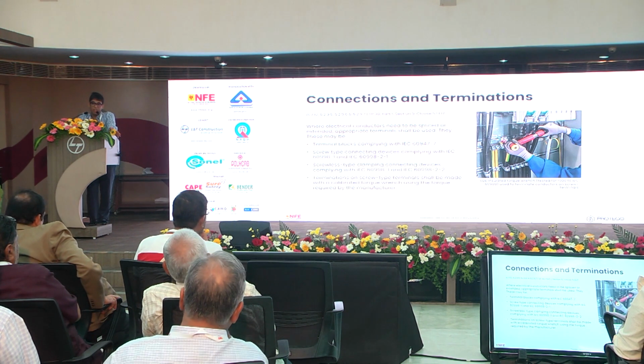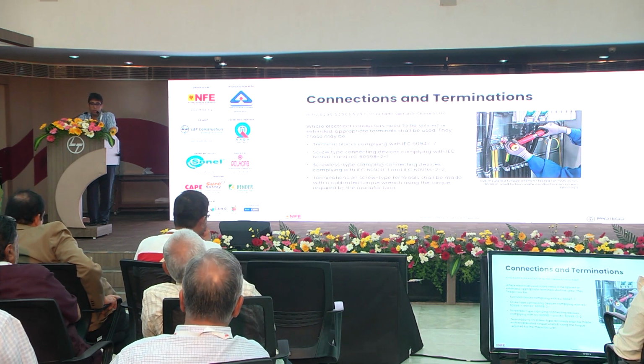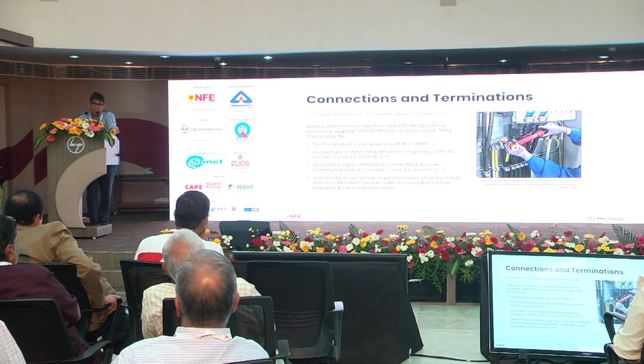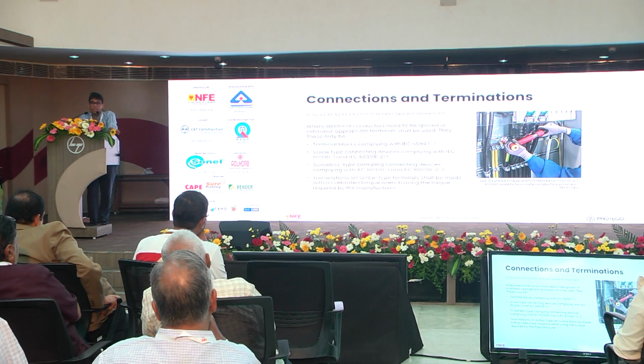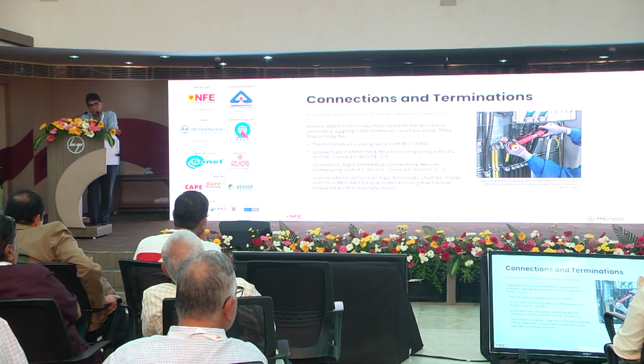If you over tighten a connection, the force on the conductor will cause the conductor to snap, or worse, the terminal block to break. Then it will affect even other conductors. So please use a calibrated screwdriver. There are a lot of manufacturers that make this. It is a very common tool.